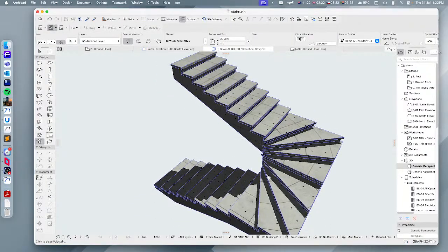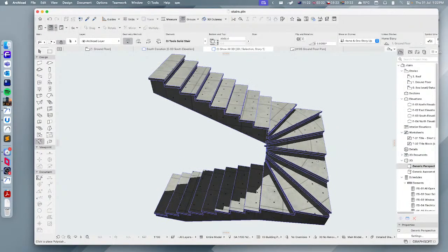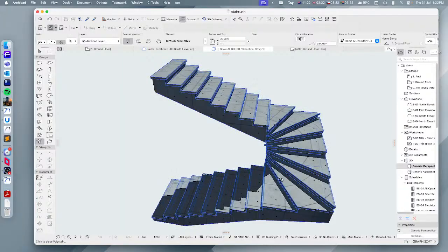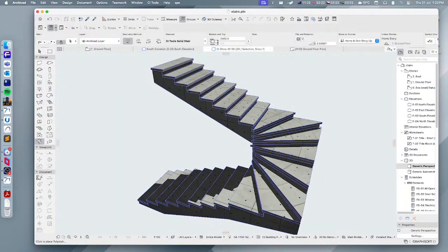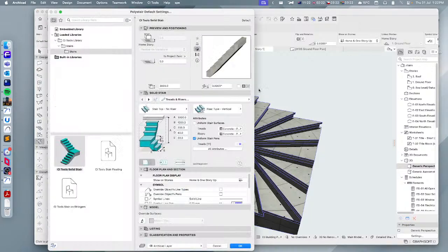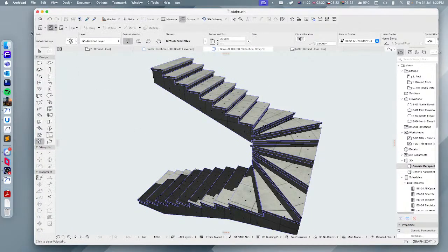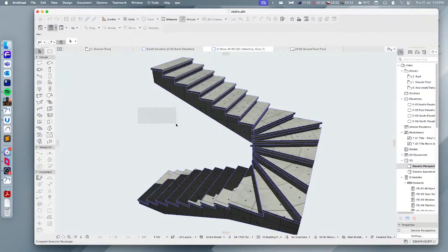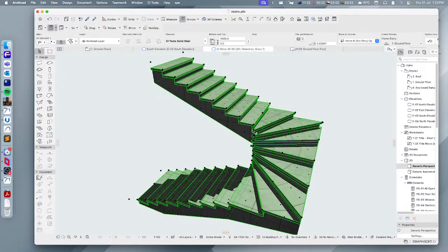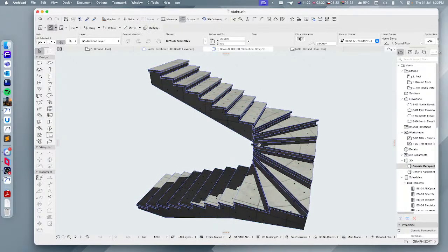Now the thing that you might notice is that we've got, what is it, looks like about 8 treads winding around there. We might want to change that, so we can do that nice and easily as well. And this is where we get into editing the flights and landings in the actual settings dialog. We could do this by eye as we go, by zooming in really close and that sort of thing to make sure that we're getting the turn radius we want.